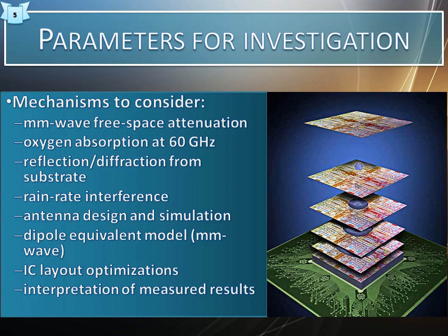Each parameter considered and researched are summarized here, and form an integral part of the models and equations used to construct the mathematical, electromagnetic, and electronic models to represent the millimeter wave signal. Free space losses are considered high-frequency losses, and they are dominant at millimeter wave frequencies and quantified within this research. Oxygen absorption within the 60 GHz band is a dominant factor and therefore also included as a notable attenuation factor.